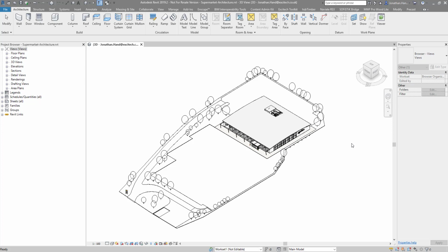Today I'm going to show you a workflow I've been testing, and it's involving Revit. I'm going to link it to the database export, which I'm then going to link into Power BI and then link that information into BIM360. So I'm in the Revit 2019 environment.